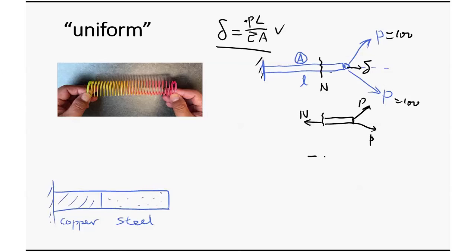Now, what's the N? Let's say minus N, write the equation of equilibrium. Minus N, then plus P, how do you calculate the force along this axial direction? P cosine of this angle, alpha, right?